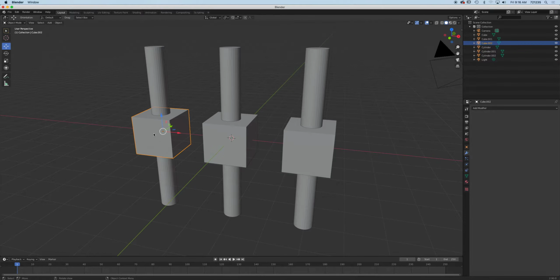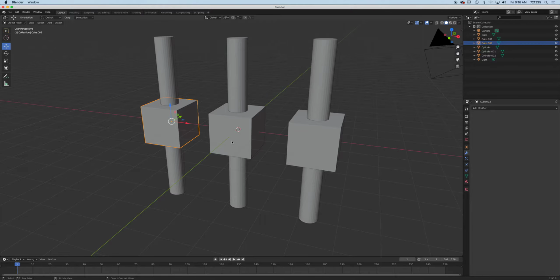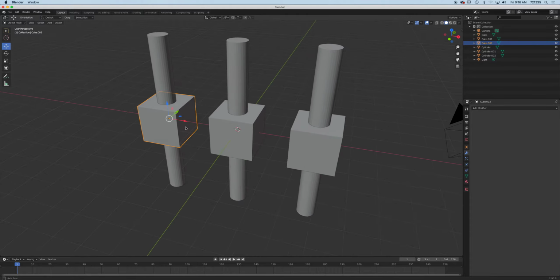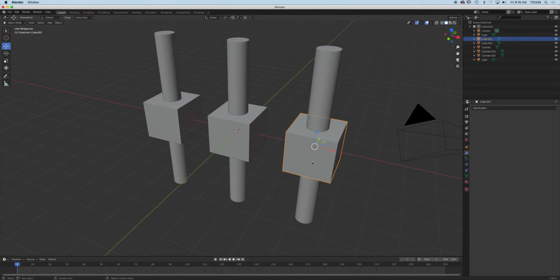So the very first one, we're going to do difference, union, and then intersection. All right. So in Boolean modifier, you always apply the modifier to the object you want to keep. What we want to do here is get this cube and then punch a cylindrical shape hole in the middle. That makes sense? Just kind of punch it in. All right. And then on this one, we want to combine the two together. And this one is intersect.